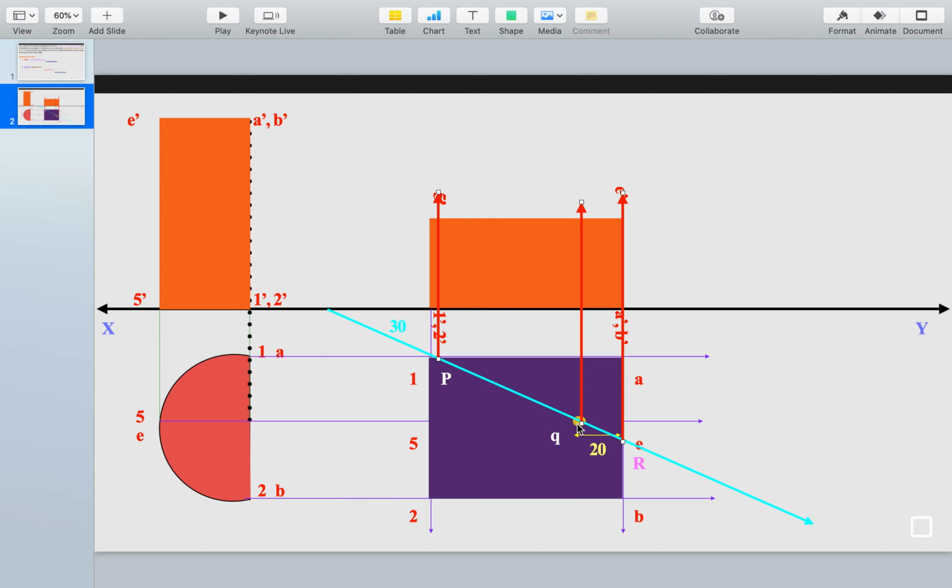So PQR, these are the projection lines. It is not existence. Remember that for our understanding purpose, just I have drawn by a different color and big line, it should be a faint line. Now I will locate this point PQR in a front view.